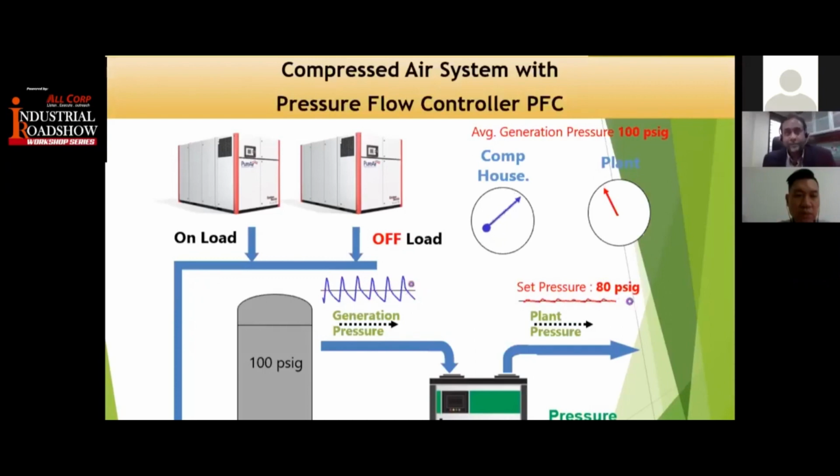So you know what the effect is if the harmonics level is high in any building. It will make your main incoming neutral cables become hot, and this will cause a heat problem, and it can also cause fire in the plant, right? So care must also be taken over the harmonics level. If you reduce the harmonics level, you are not going to get any saving, but in terms of safety, it's very important to check the harmonics level of your plant, right?